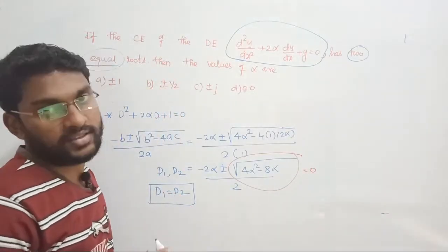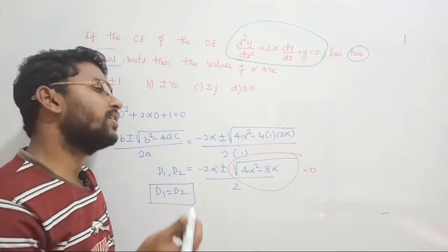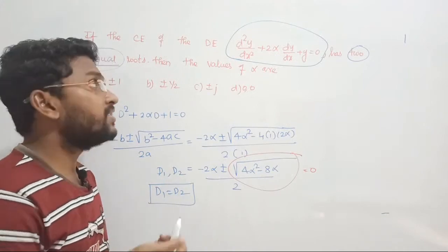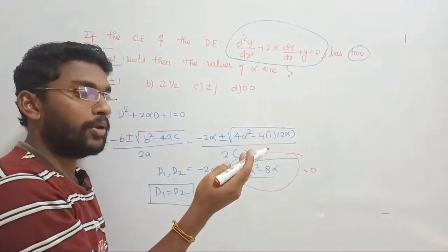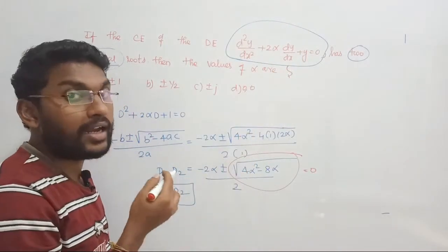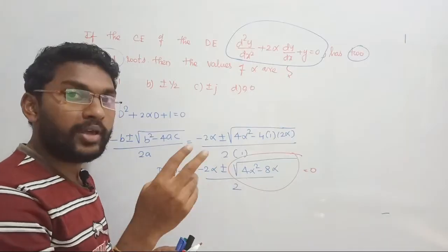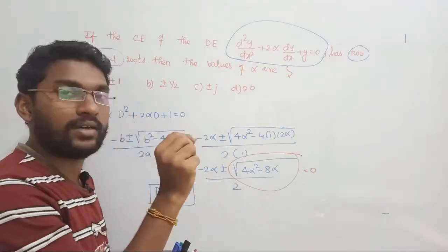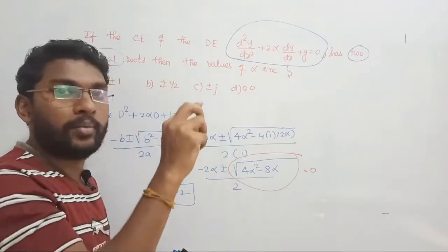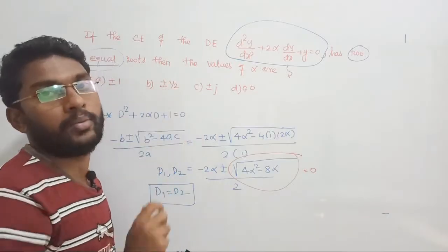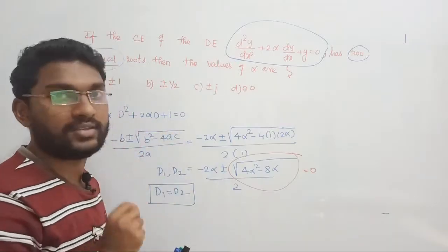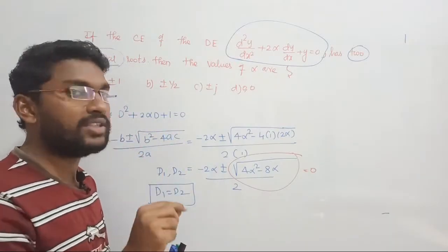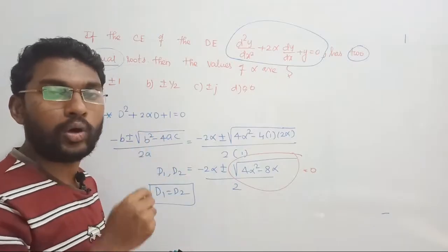In critically damped system, right, what we saw, just go to your control system, we saw there are second order systems. Given it is the second order system, there are 4 types: undamping, underdamping, overdamping, critical damping. Critical damping means, 2 roots are being repeated and they are being placed on the real axis, right? That means both roots meet at the same point at the same time. And the imaginary part is completely going to be 0 in critically damped system. That is, the value of epsilon will become equal to 1. Do you all agree with me?